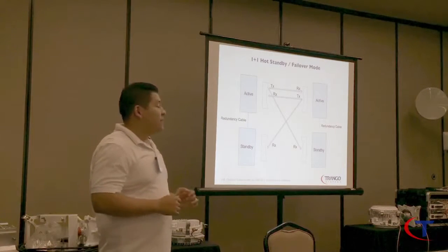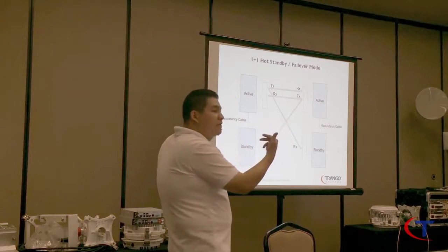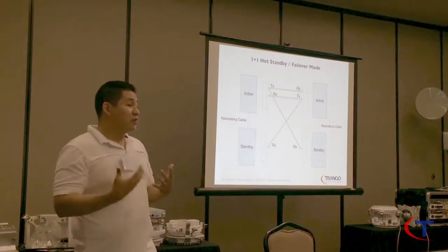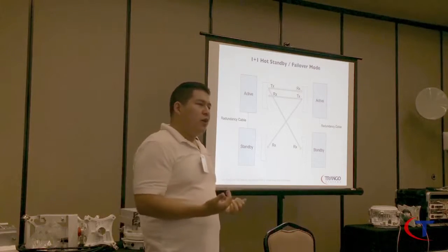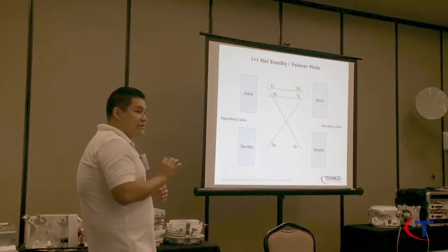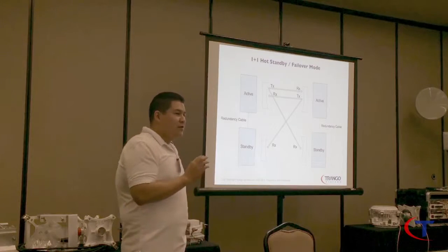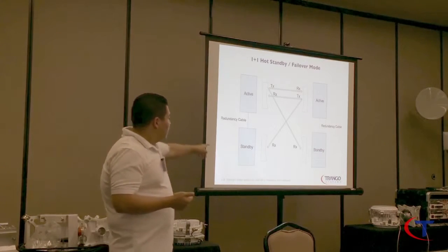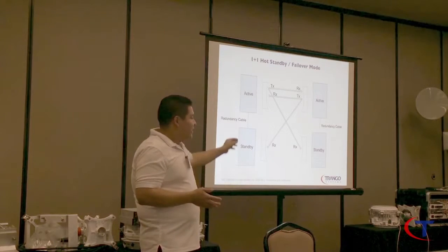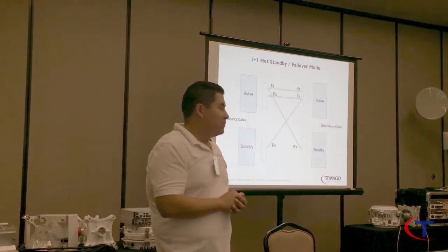1+1 has standby failover mode, as we said before. You have your main link, which is transmitting and receiving, but the standby link is just receiving. It's listening to what's coming from the far side. So when you log in and do an RSSI link test, you should see fairly symmetrical RSSI. There's going to be a little bit of loss depending on the combiner, and on frequency as well. That redundant cable, if it's not there, there's no point. That redundant cable sends the keep alive to the other radio, the slave radio.